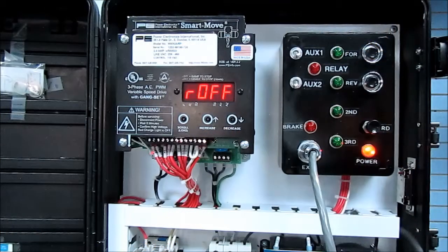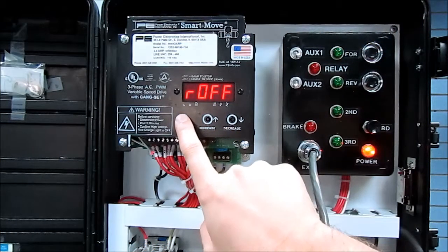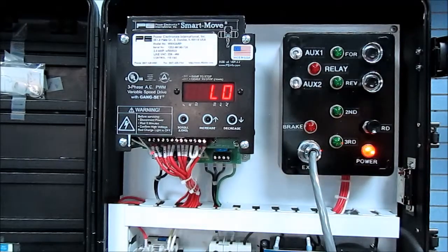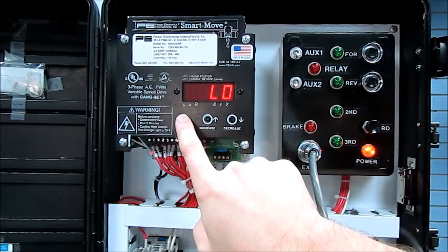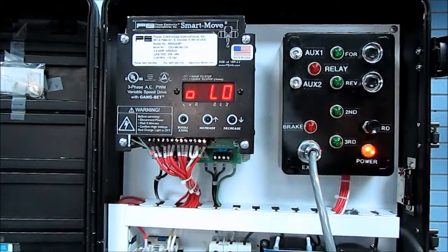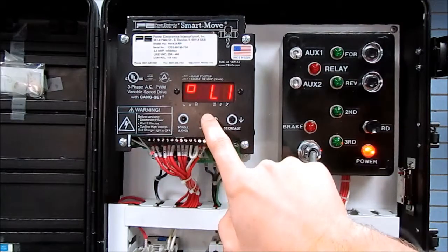When you are already in a parameter grouping, such as the L parameters, there is another method you can use to quickly get to the desired parameter called Quick Scroll. To use this feature, hold the scroll button down for about a second and let go. Notice there is now a bouncing ball indicator on the left of the display.